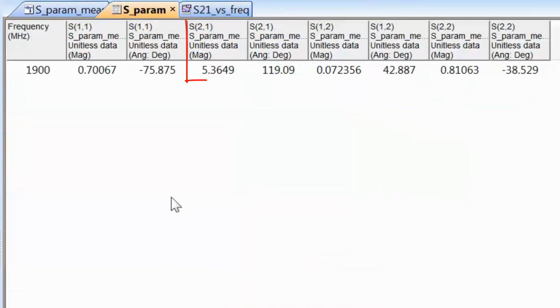So we've seen that we have some sort of gain already available for us to use, but also if we look at the S11 and S22 in terms of their magnitudes, you can see that these are such that a lot of the signal that goes into this port is reflected back, which shows that there is quite a mismatch between our source and the input of the transistor, and our load and the output of our transistor. So one would assume that if we could reduce this mismatch through the use of matching networks, then we could increase the gain of the amplifier. And this idea, of course, seems to be quite sensible. So we might as well try to do that and see what happens.